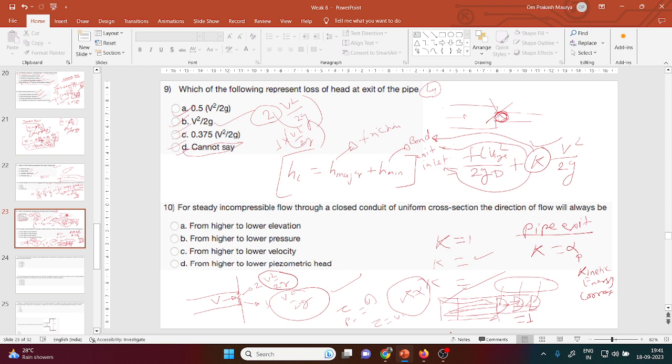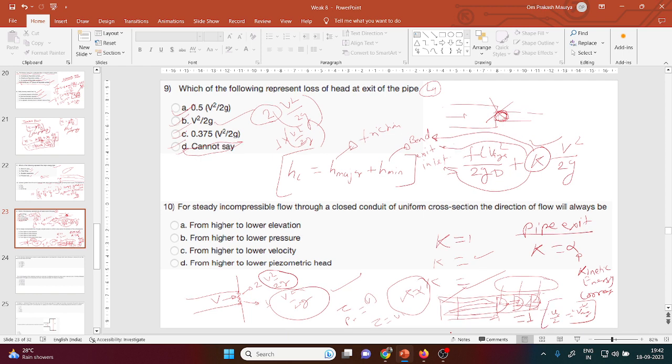So we need to always calculate the velocity, the maximum velocity in the pipe, and based on that we will design. Maximum means that you already know the maximum is related to 2 times the average. So if you want to design for the average and you are given the maximum velocity, divide by 2 and you will get the average.